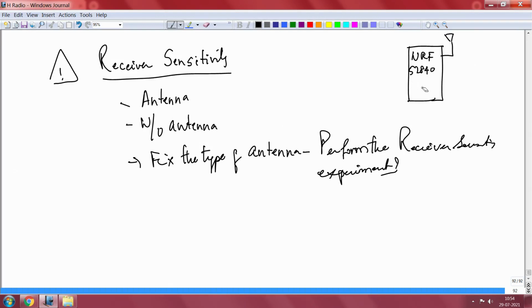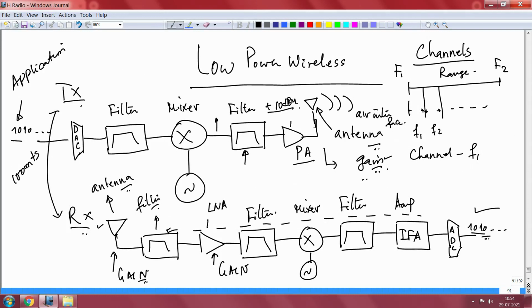The 840 in fact is so powerful, it can support either ZigBee, Bluetooth, or some other types of technologies as well. A single SOC can do all of that. Why are they able to do that? By a simple software change you can shift from ZigBee to BLE to whatever. Why is that possible? Now you know the answer, because the chain here, this chain that I showed you on top and the chain below here are one and the same.